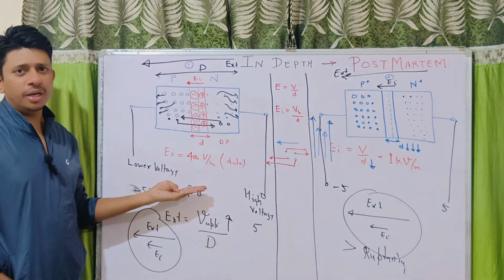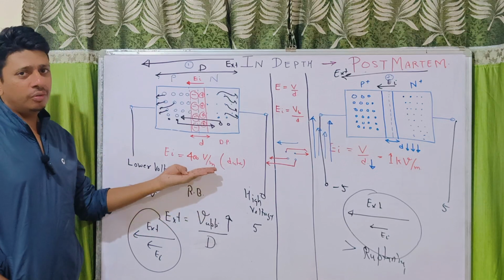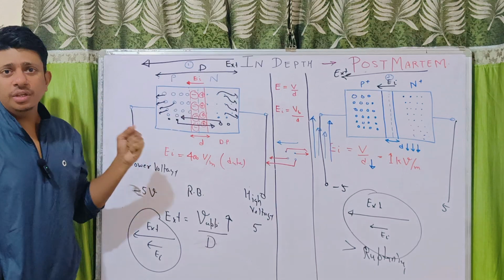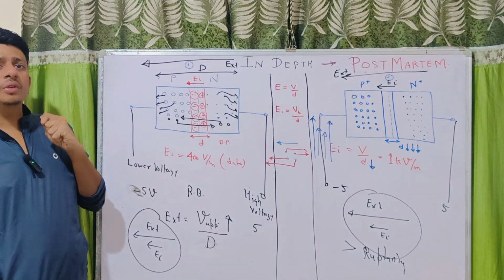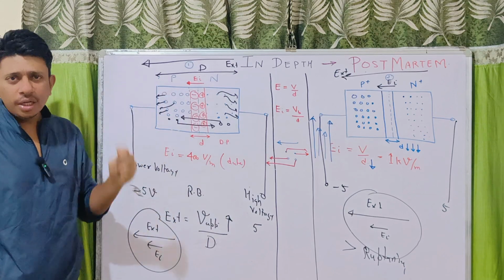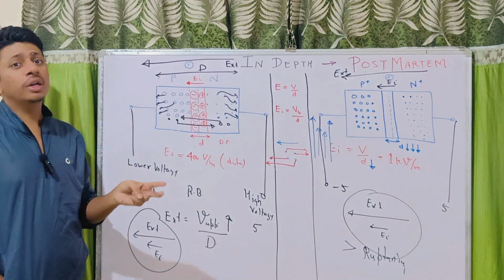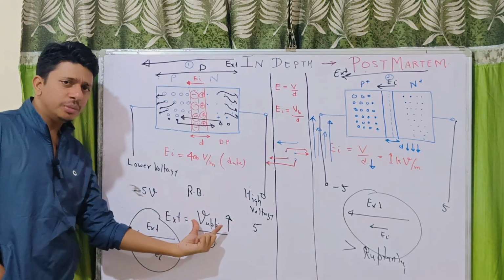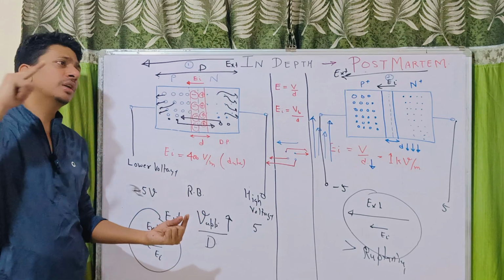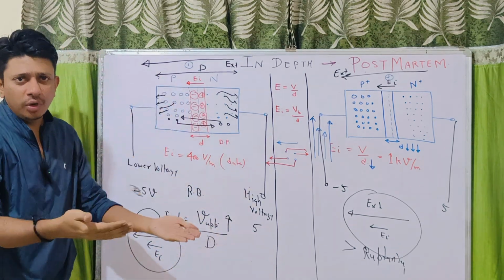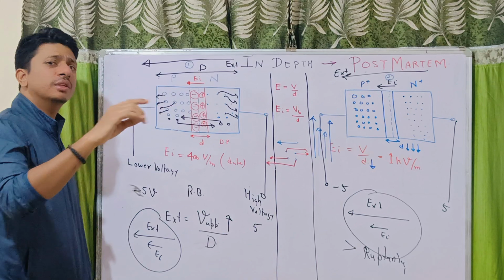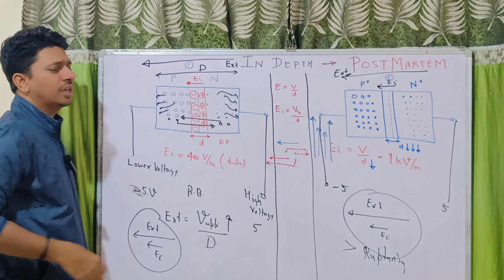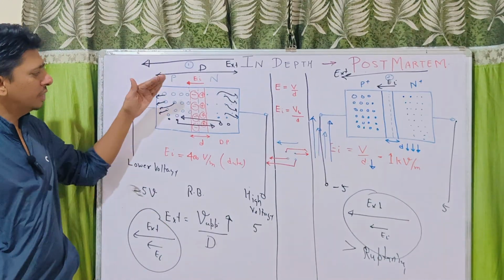As we go on increasing the applied voltage, a time will come when the electrons will get a sufficient amount of energy and they will collide with another covalent bond. It will break those covalent bonds and those bonds result in another electron. These two electrons further gain energy from the applied voltage. Now they will collide with other covalent bonds and result in 4 electrons, and this process is known as the avalanche mechanism or avalanche process, and this process results in a large amount of current flowing in this configuration.